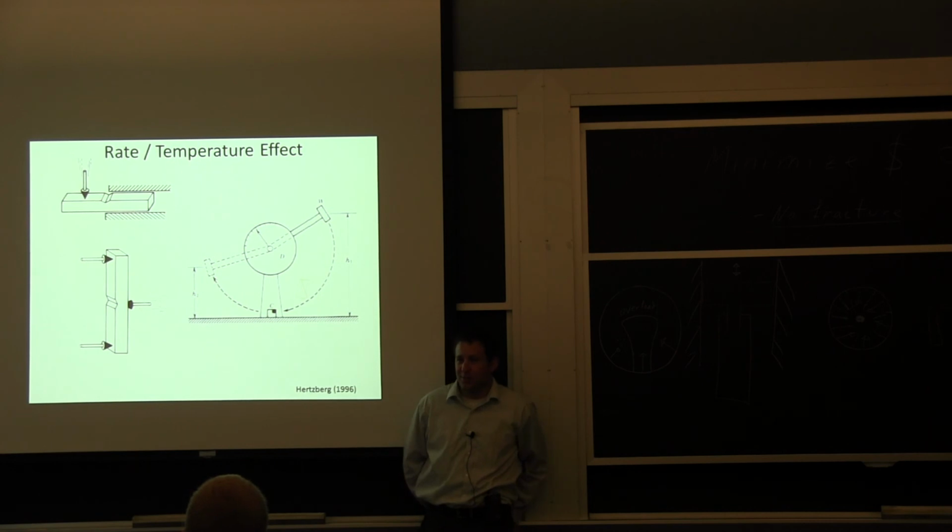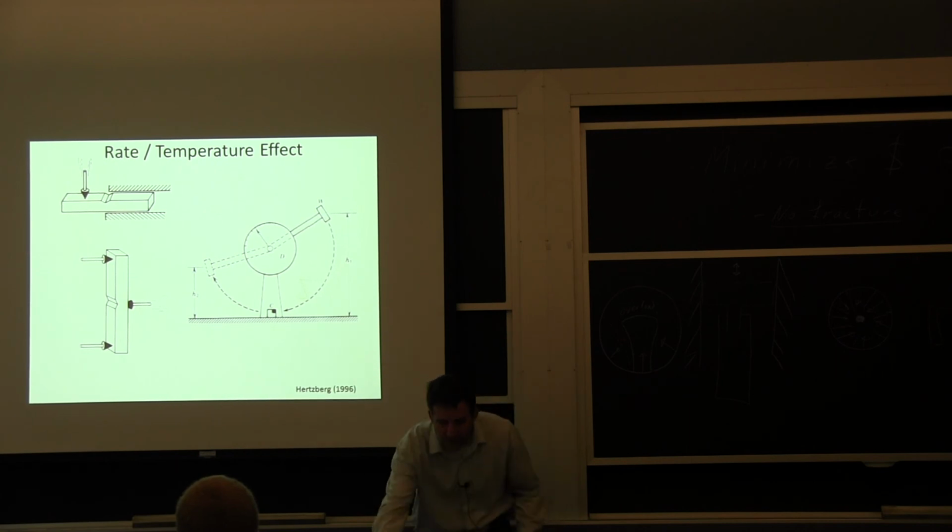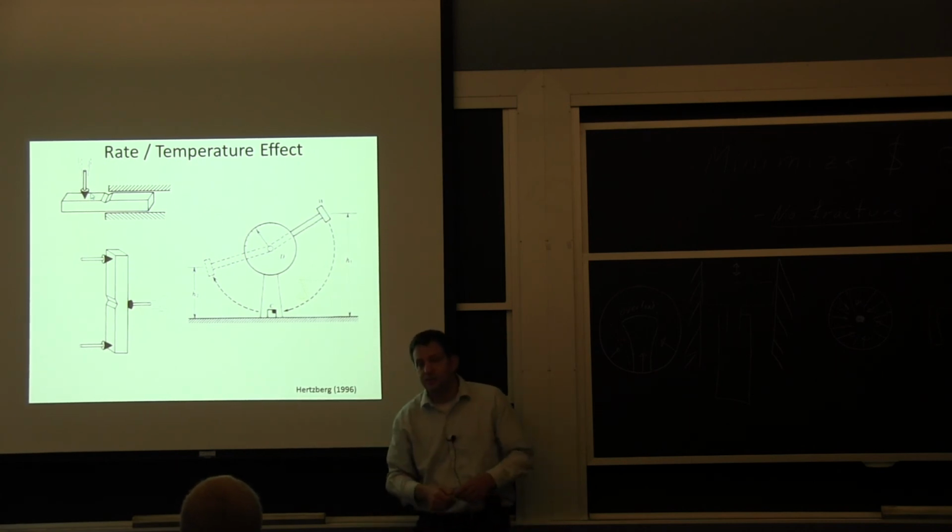So when you get the pendulum across, there are situations where you won't break the sample. The sample is just really going to stretch and open up a crack, but without a complete separation. That's if you have a lot of ductility, or you'll just break it in two pieces. The Izod type of test here, where you drop the weight, is more common for plastics.